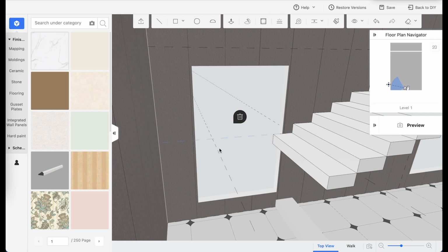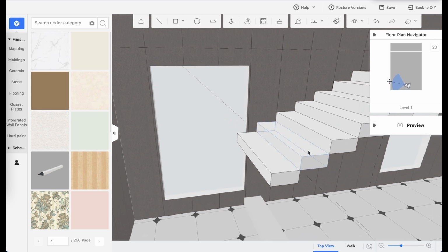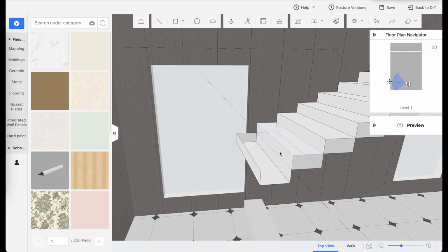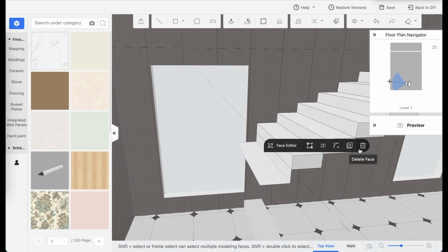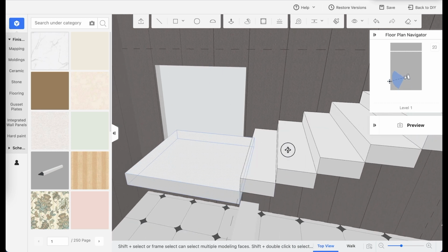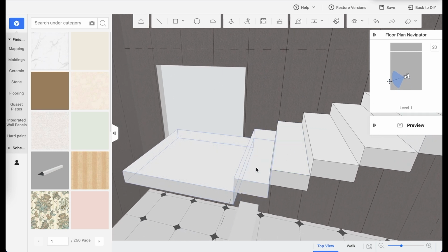So it doesn't do it. I think this is one of the annoyances that happens. But not to worry, what we have to do is delete the surfaces and re-extrude again by typing in the dimensions that we have. Hit extrusion, 48, and there you go. And group that again.